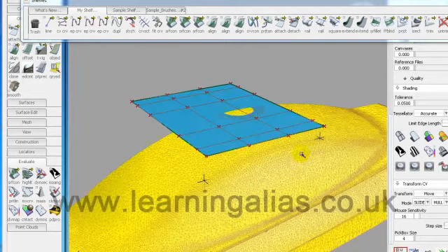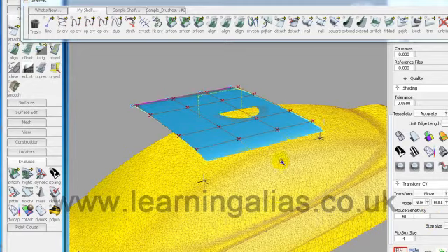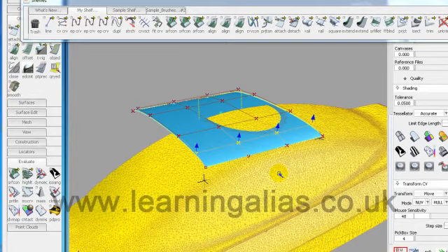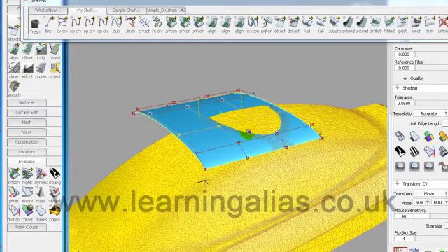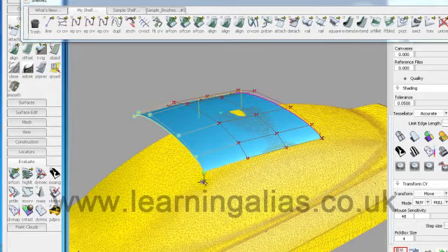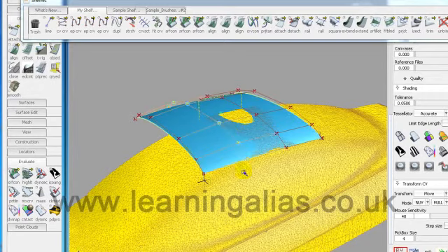Go into shade. You can use quick shade if you've got a small computer. Now we need hull and NUV, and then the sensitivity, probably put it in the middle there, and start pulling down the surface, and do things kind of together. Don't try to do everything with one CV or one hull. Okay, so I want to see the mesh just like that, and then I'm going to start pulling down the surface at the ends, and as I pull it down I have to lift that up and pull this one down.